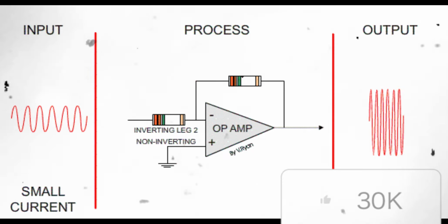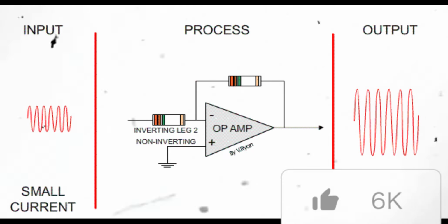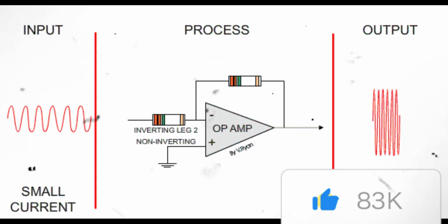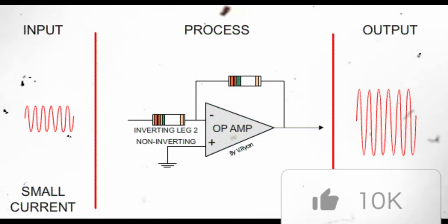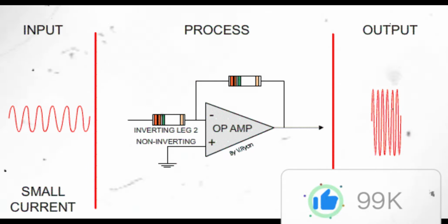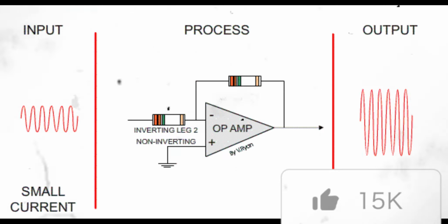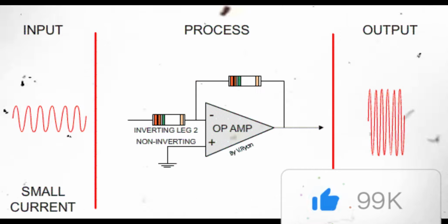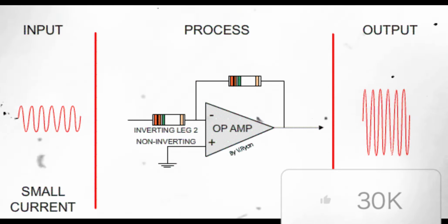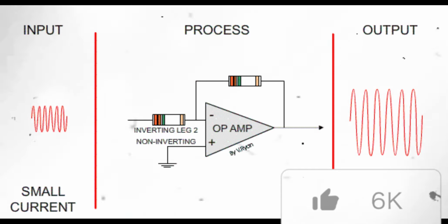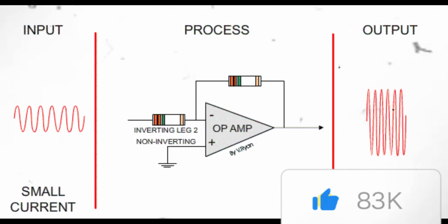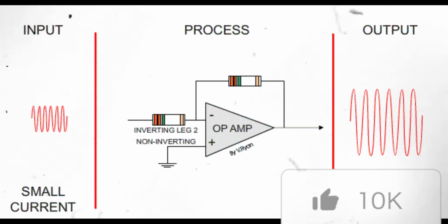Bandwidth and gain bandwidth product. An optimal op amp will have an infinite bandwidth and be able to amplify any frequency signal from DC to the highest AC frequencies. However, actual op amps can only amplify signals through a specific range of frequencies.